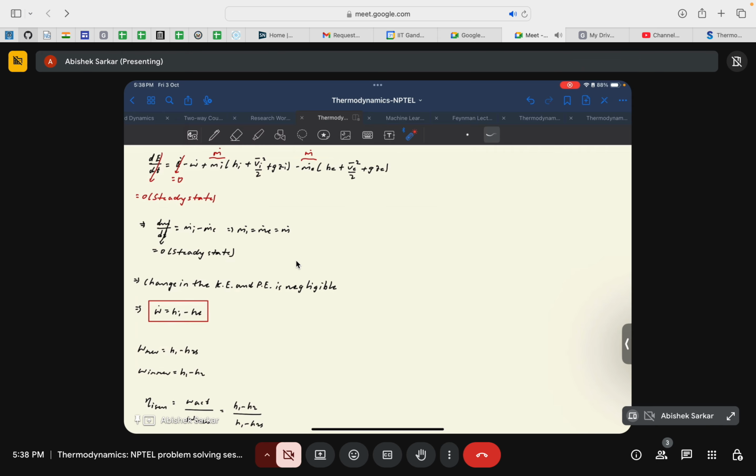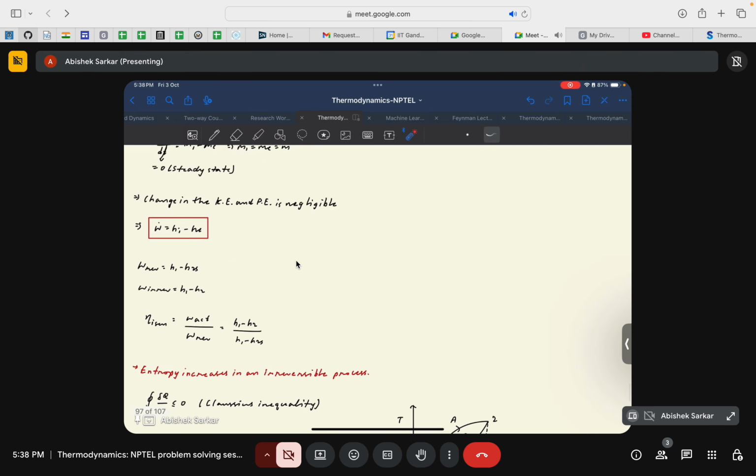The isentropic efficiency is the quantifiable parameter that is used to understand these irreversibilities. It is defined as the ratio of the actual work done divided by the reversible work done. The actual work done would be the irreversible work produced, considering the real life scenario.